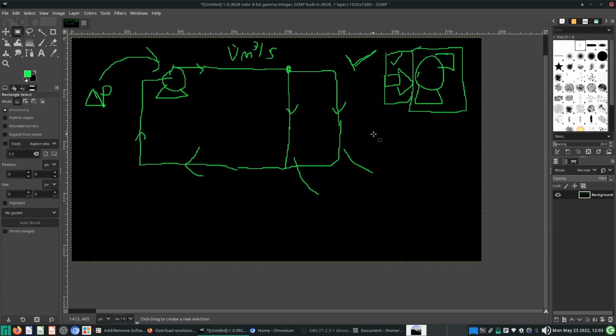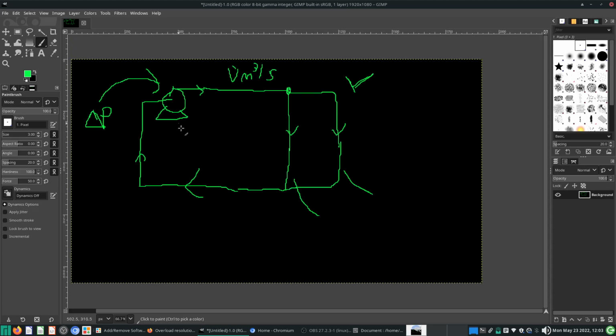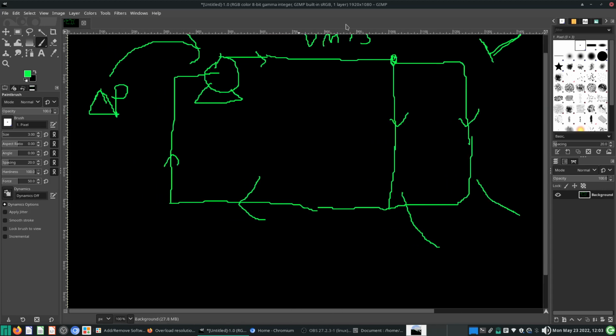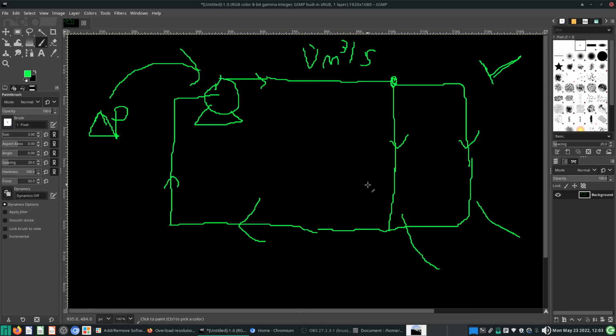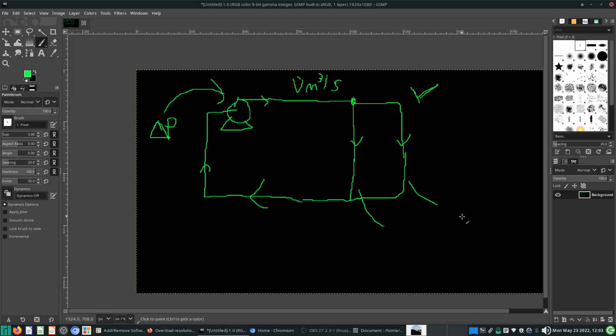I want a real-time, dynamic simulation of fluid flow schemes and setups. So I need these fluid flow equations to solve instantaneously or near instantaneously, but I do not really need all the chemical equations there. I will probably add the heat transfer equations later and solve them in parallel with the fluid flow equations, so they're loosely coupled. That way I can have the whole thing running in real time, because calculation time is of the essence, so you do not want to burden the solver too much.